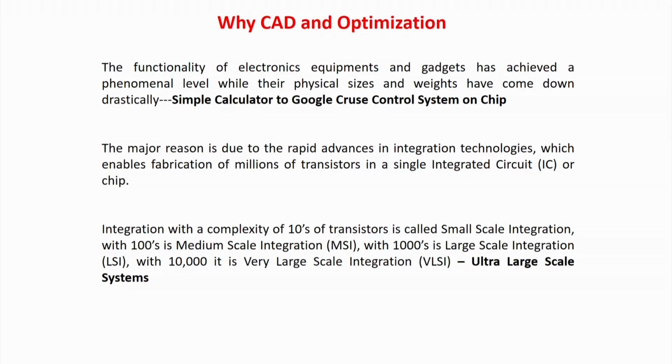Therefore, in such cases, all these steps of design, like taking a specification, converting it into high level synthesis, then an RTL design, then gate level, and finally laying it out, and even testing and verification, nothing can be done manually. You will have to have some CAD tools to do that. That is a subject which all of us might have heard of, called CAD for VLSI. If you look at the CAD for VLSI perspective, it discusses how we started with tens of transistors in small scale design, when it was a simple calculator or a simple logic circuit.